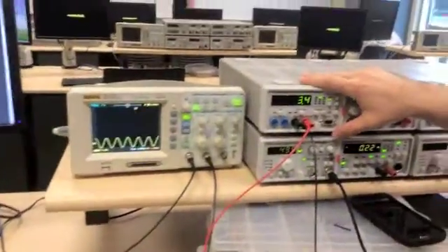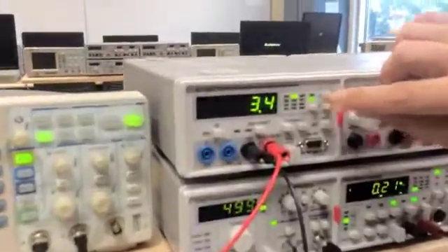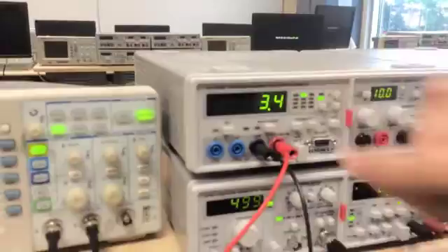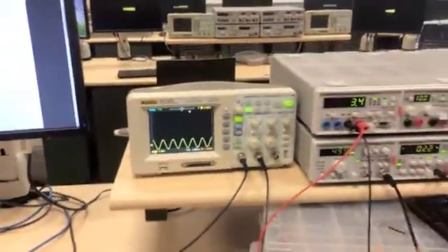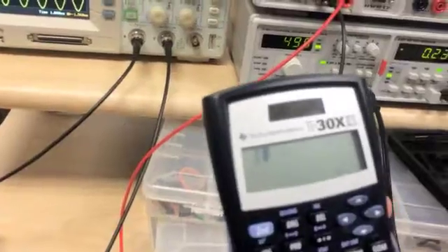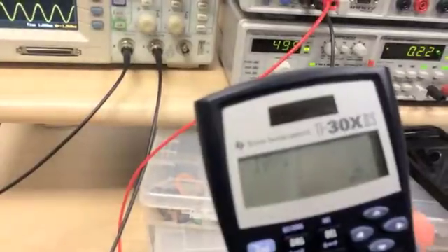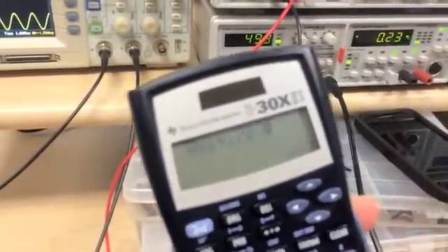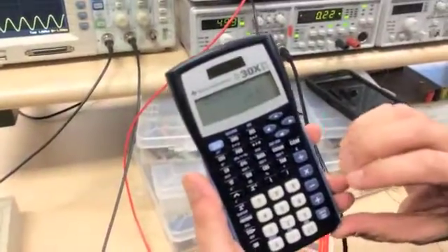Here we have a multimeter, which is set to volts in AC world, and we're going to measure the root mean square volts. It is measuring 3.4 volts root mean square, which is consistent with our calculation. 10 volts peak to peak divided by 2 gives the peak voltage, 5 volts peak, and then times 0.707 will give root mean square volts, 3.535. Consistent because our method was old school, we have small error.